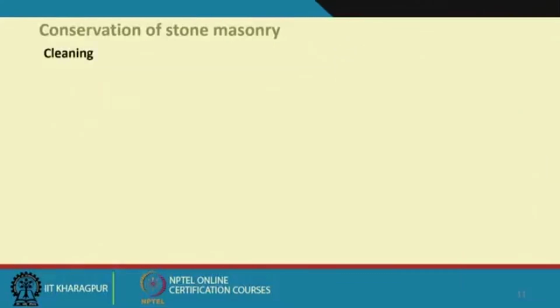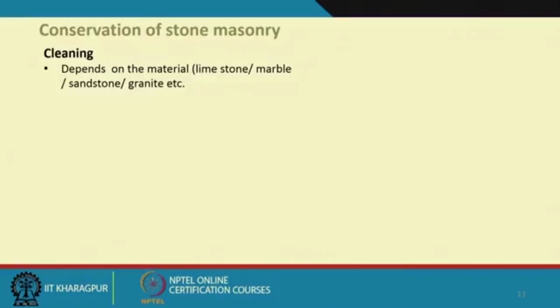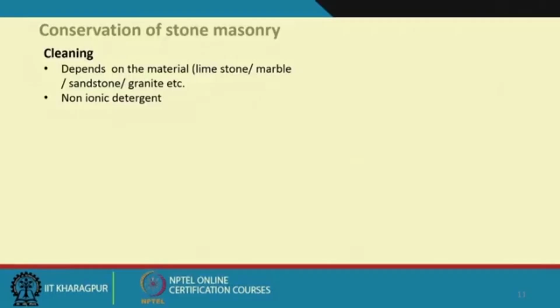Now, when we talk about the cleaning, it depends on what the material is, whether it is limestone or marble, sandstone or granite, and the cleaning agent should be decided accordingly. It should be a non-ionic detergent, not the normal detergent we use at home. Removal of moss and lichen is a part of the cleaning process.